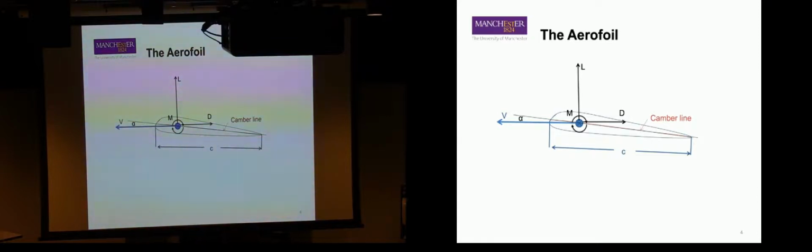Now, we have many different types of airfoil, different descriptions. Some of the most famous are the NACA, or National Advisory Committee on Aeronautics, series of airfoils, and there are several of those. What's nice about those is the numbering scheme for that airfoil, be it a 4-digit airfoil or a 5-digit or 6-series airfoil, describes the shape of the airfoil, the curvature of the leading edge, the thickness of the airfoil, and the way it's cambered.